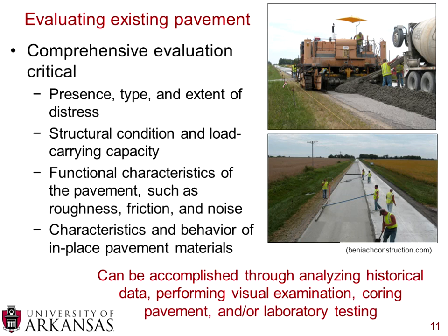It's important to know some of the functional characteristics, and functional characteristics include items such as roughness, friction, and noise. This will help you understand what you're going to be putting on top and how that's going to interact with what's in place. And then finally, you want to know the behavior of the in-place materials. What's actually happening in that pavement at the time. Is the subgrade in good condition? Is the subbase in good condition? Do you have pumping? Is water coming up to your roadway? All these types of things. These are just good things to know about roadways when you're doing any sort of evaluation on them.